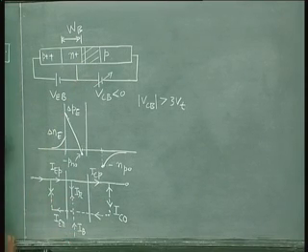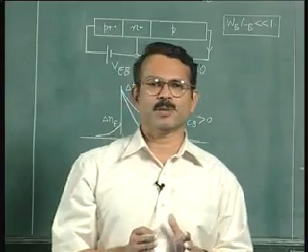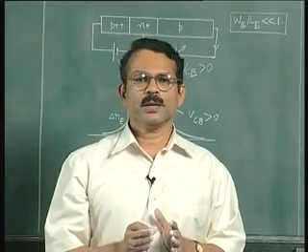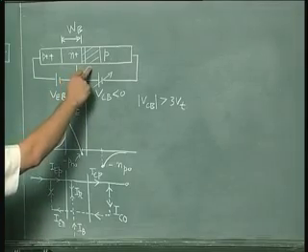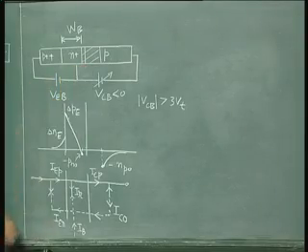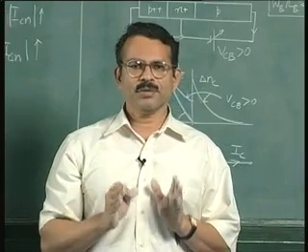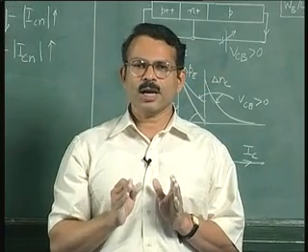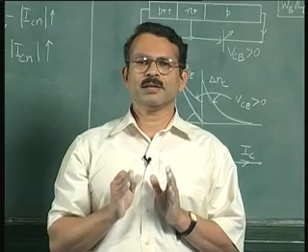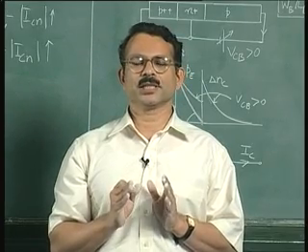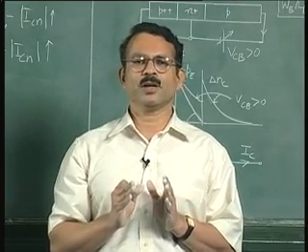So in effect what we can say is that the collector current is not significantly affected by the presence of reverse bias. Okay. Now if the reverse bias is very large, of course this junction can break down, but so long as we don't go to such high voltages, we find that the transistor action is essentially remaining unaffected. The only difference is that there is a small additional current in the collector, that is a reverse saturation current of the collector base junction, in addition to the situation we had for zero bias.